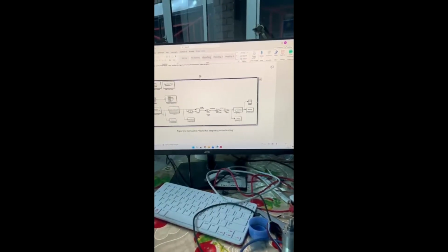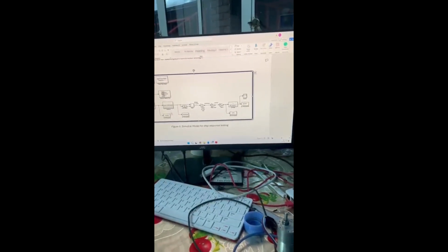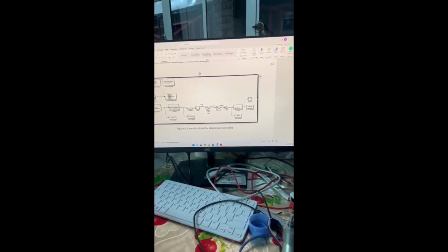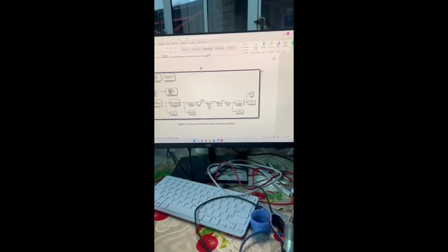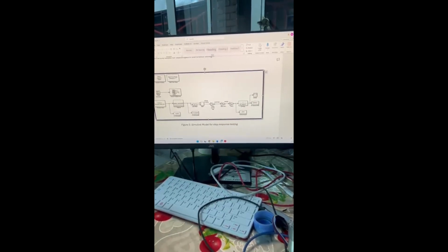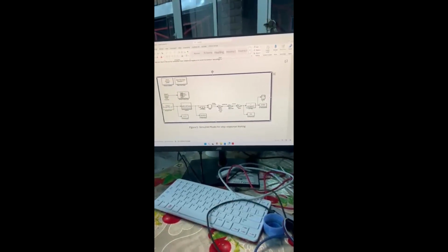There we have the Arduino encoder read, which reads the physical encoder signal and sends a value to this variable that's called count. And then later on, we can use that to plot a graph. Then going on to this part, a digital pulse is constantly sent to Arduino 1, and this is the gains and the filters, which is used to improve the signal and the graph.